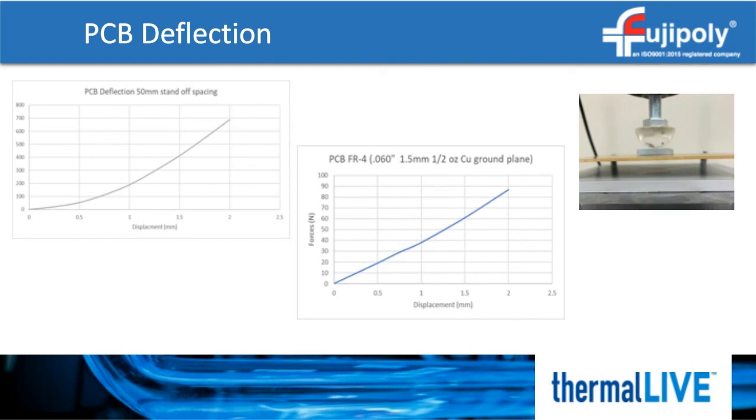I need to bring up an important point though. This doesn't mean we can simply create standoffs that are close together and apply as much force as we want. The PCB is still under a lot of stress. So are the solder joints. The standoffs are also under a lot of stress. So basically anything in the load path is going to be strained. Managing the deflection on the board is critical. That starts with understanding the characteristics of the PCB and the thermal gap filler.